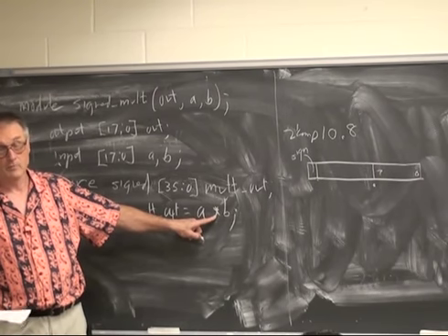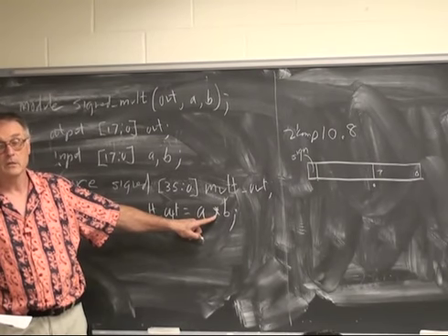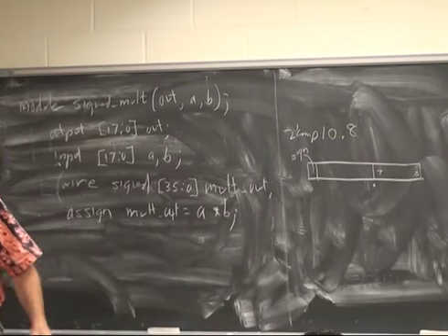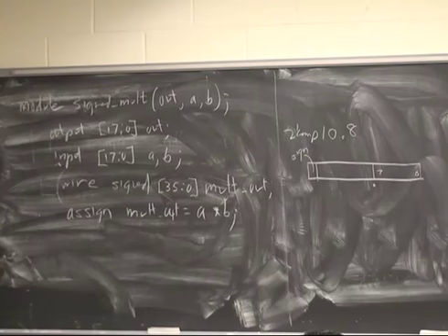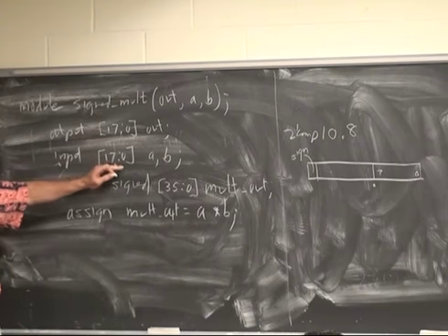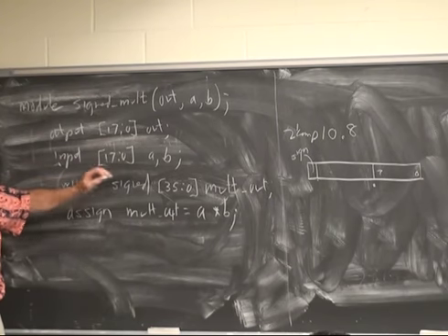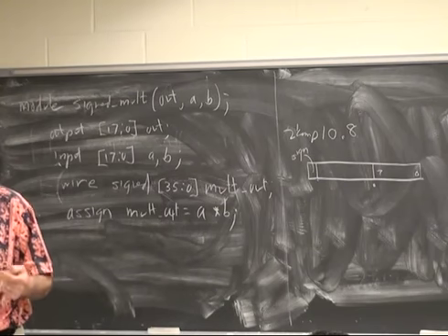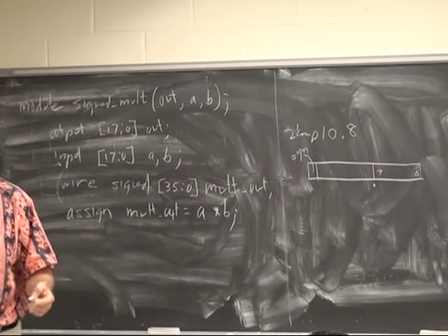It uses multipliers. Alex? So is the format of the hardware that instantiates going to be 20 bits of integer and 16 bits of fraction? Just doubles. It doesn't know anything about bits. So it's just going to do an integer multiply, and you have to force it into the right format by choosing the correct output bits.